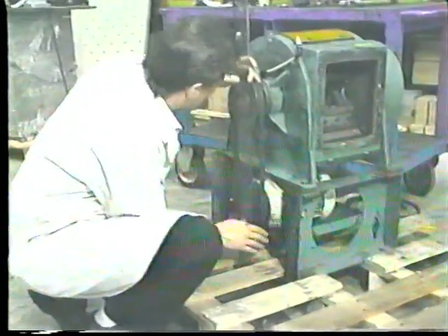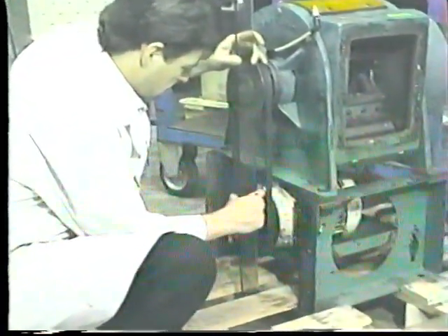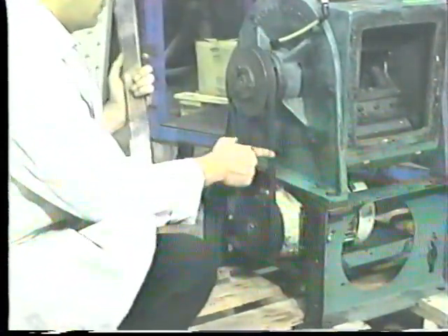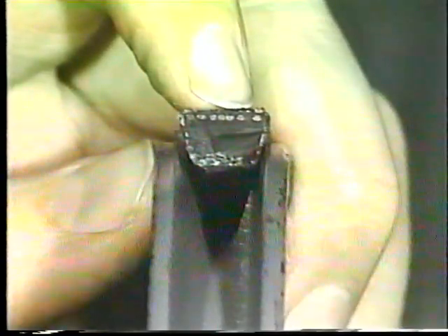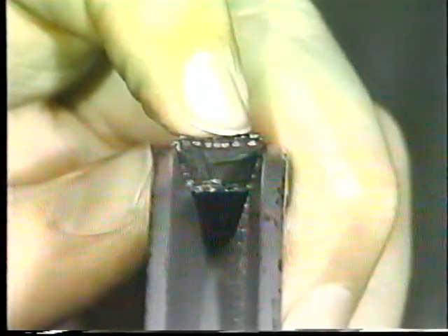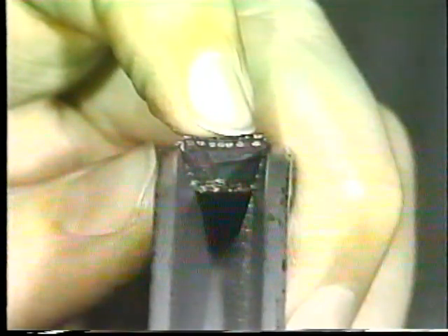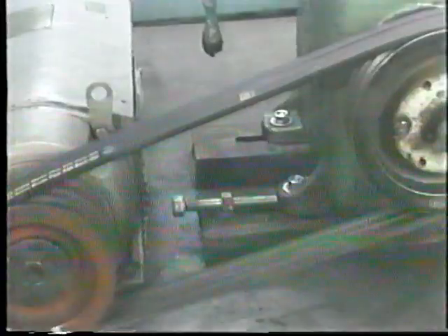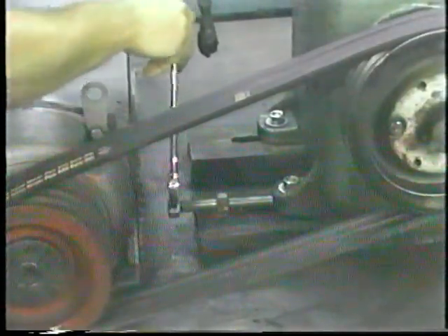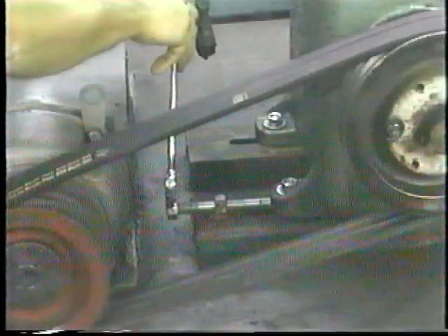However, because they are so reliable, people often take them for granted and fail to follow proper installation procedures and maintenance practices. The V-belt gets its name and its gripping power by wedging its V shape against the inside of the groove in a pulley, usually called a sheave. When a V-belt is installed, tension is applied by adjusting the distance between the drive motor and the driven equipment.